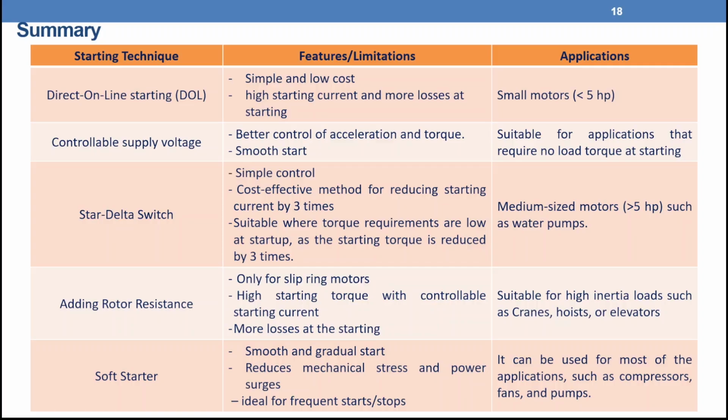So the optimum solution is the soft starter if the cost is not a limitation. You have a smooth and gradual start, which reduces mechanical stress and power surge. It's ideal for frequent starts and stops. So this method can be used for most applications, such as compressors, fans, and pumps.